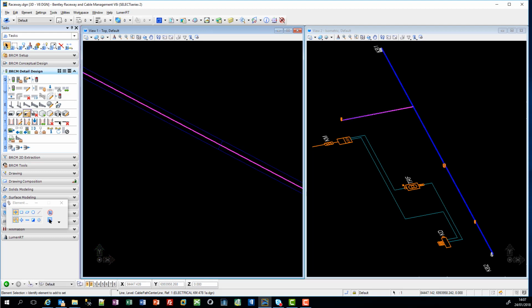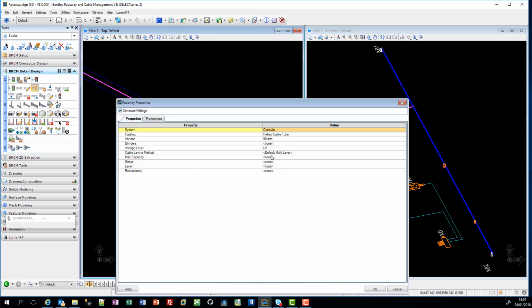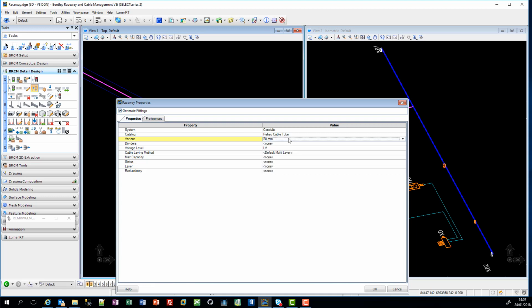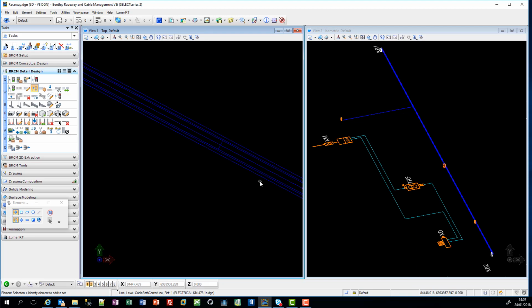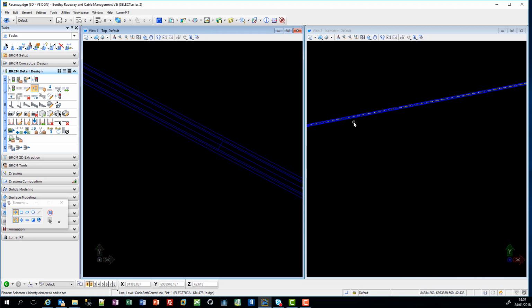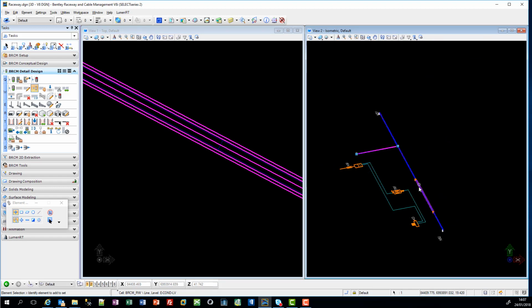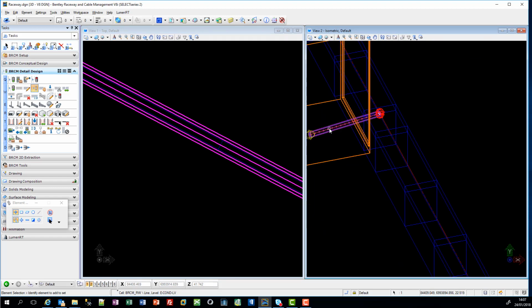So if I select that center line and use the Raceway generator, here it is possible to select, for example, conduits with manufacturer selection and a variant from that manufacturer, let's say 90 millimeters. And here, for example, for low voltage cable, and that will create here a separate conduit inside the drawing.